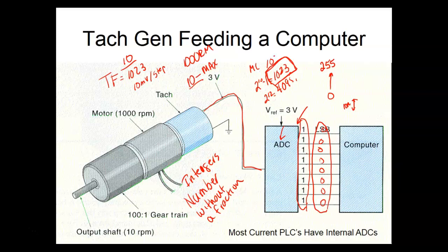So this is basically what we're getting out of our A to D. So if I'm dealing with integers and then I calculate, what did we calculate? 9 point something. Well, there's no such thing as a 9 point something integer. So our A to D converter is giving us integers, but it only switches between steps. So that means if I put 2 millivolts on the input, this thing would still show me 0. Then when it went to 10, it showed me a 1. And then all the rest of them would be 0.